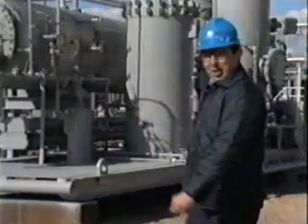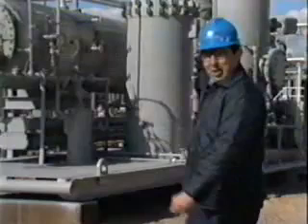Separating liquid hydrocarbons from glycol before they enter the reboiler provides several benefits. It reduces the load on the carbon filter. It prevents carbon from building up on the reboiler fire tube. And it prevents glycol contamination in the still column, which can result in flooding, glycol loss, and possible damage to the column. Two-level control systems are typically installed on gas condensate glycol separators.